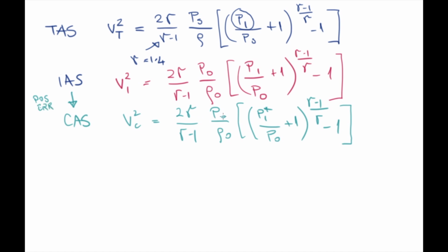This is only really possible on computerized aircraft that have an air data unit and have some type of digital display that is able to do the correction between pi and pi asterisk. Now, this still isn't the genuine article, because it still has the sea level static pressure instead of the actual static pressure.